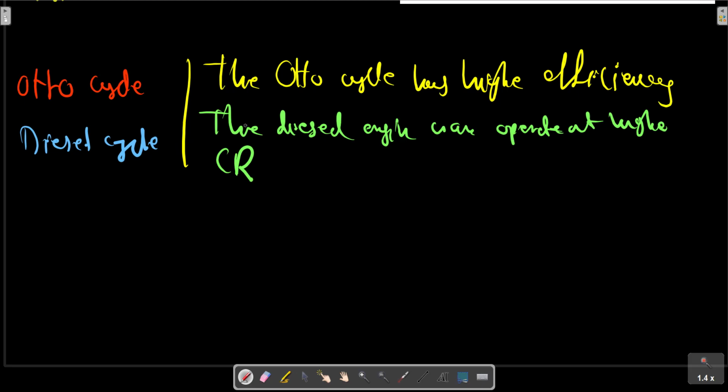Therefore, we may compare an Otto cycle and diesel cycle, and in each case select a compression ratio that may be achieved in practice. Such a comparison can be made by considering Otto cycle and diesel. The maximum pressure and temperature are the same for both cycles, which means that the Otto cycle has a lower compression ratio than the diesel cycle. This is evident from the TS diagram, that in this case the diesel engine cycle has the higher efficiency.